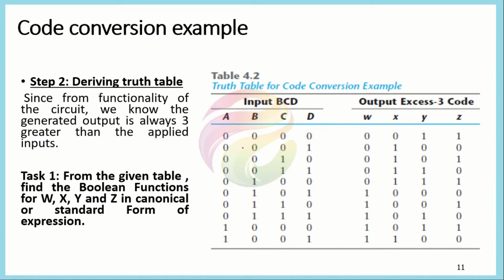Each combination represents an equivalent decimal number. We know that the BCD numbers start from 0 and the last digit that is represented is 9. So these are the set of BCD codes. Similarly, we can also define the XS3 code. We know that the XS3 code is equivalent to adding 3 to the decimal or binary equivalent of the number. These are the equivalent XS3 codes.